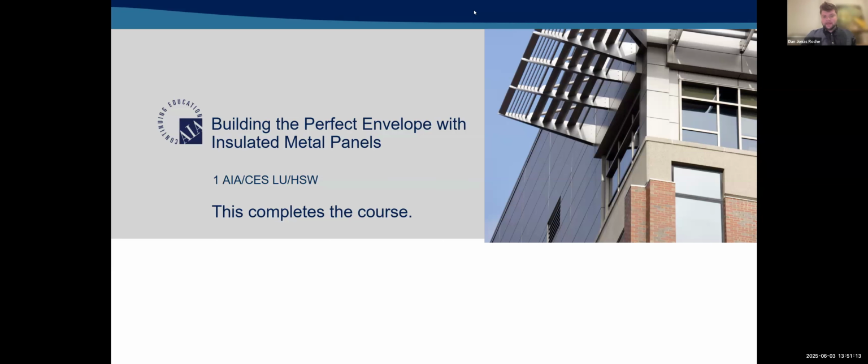Is an insulated metal panel considered continuous insulation? Yeah, we kind of talked about that earlier. It's not that the definition of continuous insulation excludes metal panels, specifically those with panel joints. But I like to call it consistent insulation because it's outside the structure and you still get a really good U value.